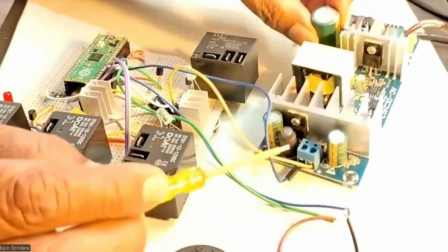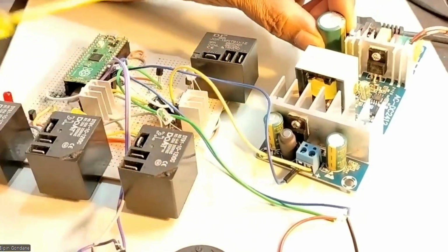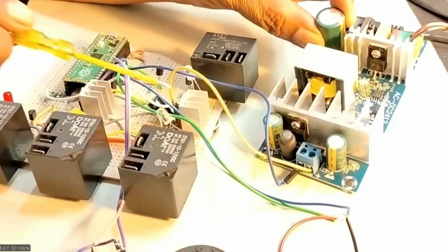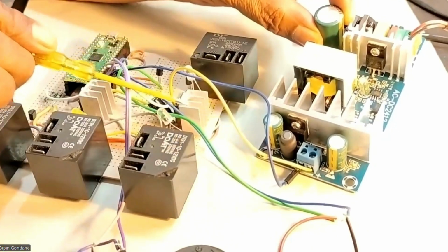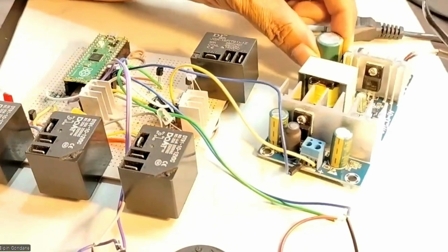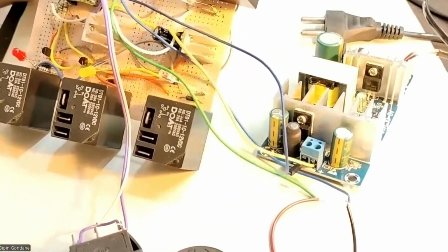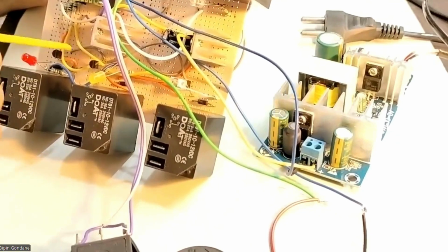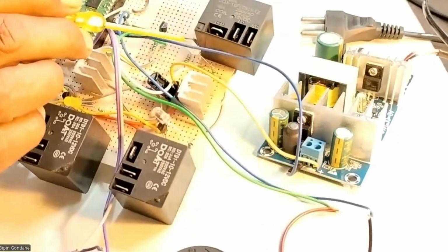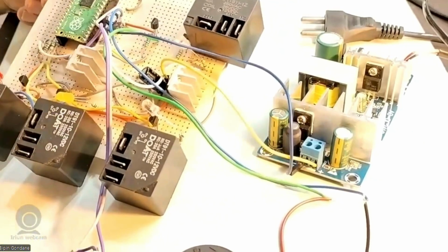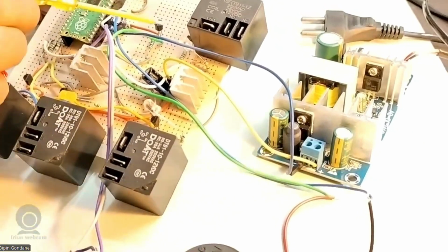You know SMPS, I hope you all understand. You can refer to my other videos. SMPS stands for switch mode power supply. So this 24 volt goes to this regulator. From here, 12 volt runs all the 4 relays. Of course, the relays and the transistors. For each relay, you can see here, I have put transistors 1, 2, 3, and 4. And this transistor is for running the buzzer. So 4 relays, 4 transistors, and for the buzzer, 1 more transistor.